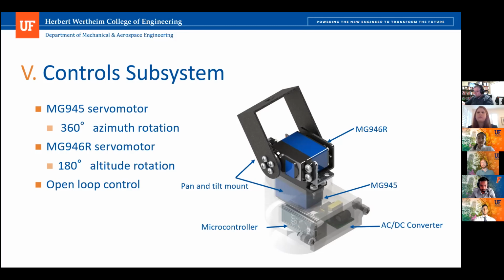This controller does not have a dedicated motor controller. Thus, the servos must be powered in conjunction with the AC-DC converter. The microcontroller will only be responsible for generating pulse width modulation signals for the servo. This particular microcontroller has a low power consumption at less than 0.5 watts.